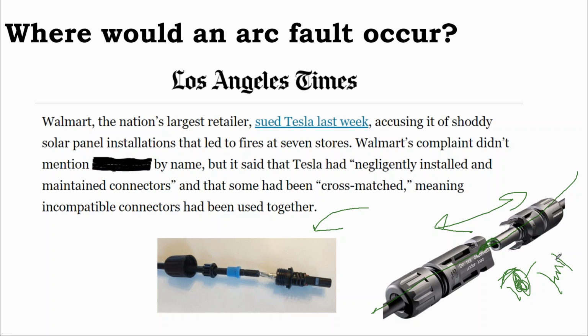If there's not much arcing, just some arcing, the rest of the electricity is still going through the circuit. If your inverter doesn't have arc fault detection, you could have a workmanship issue on the roof starting to catch a fire on your roof, and you wouldn't do anything about it. Now, as in other industries, but particularly true with the electrical industry, it comes down to good workmanship, and particularly on commercial projects, you should have electricians do this work.